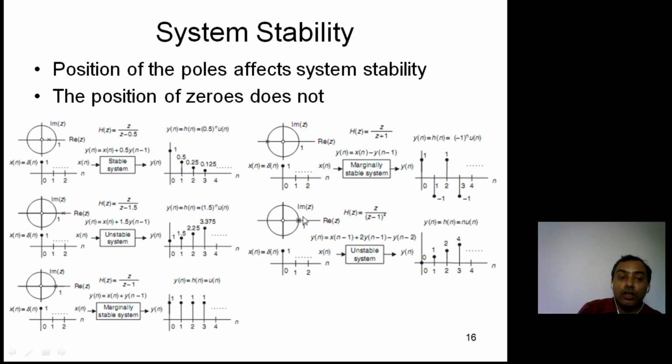That's the concept. One example of how the system is described: you see one sequence, and how the transfer function is obtained. We have x and y, and we have to convert this into the z transform, with z power minus 1 for y[n-1]. So this goes to the bottom, and we get the transfer function. Then on the basis of that you can say stable or unstable, and accordingly you can draw the system's unit step and impulse response. Now, the discrete Fourier transform.